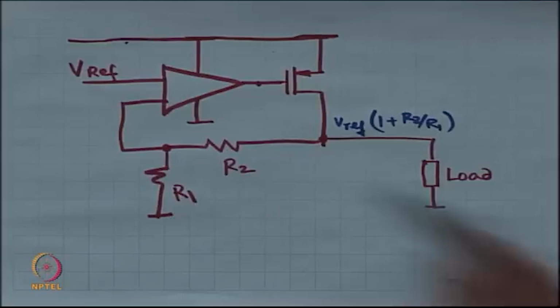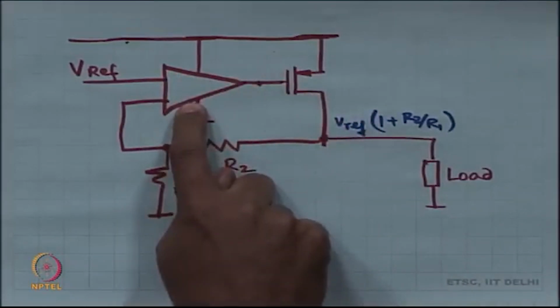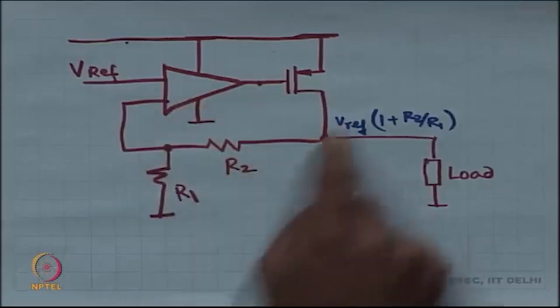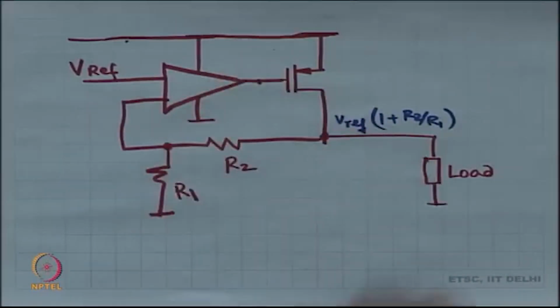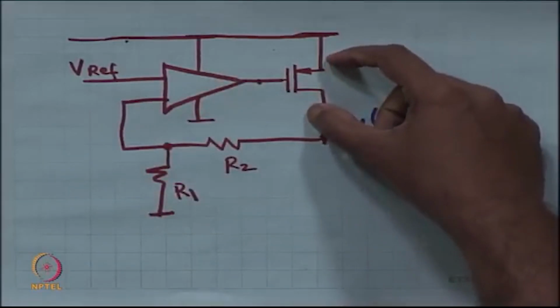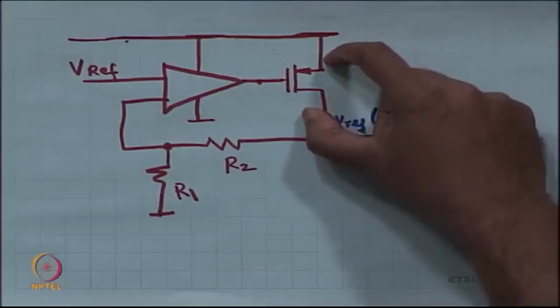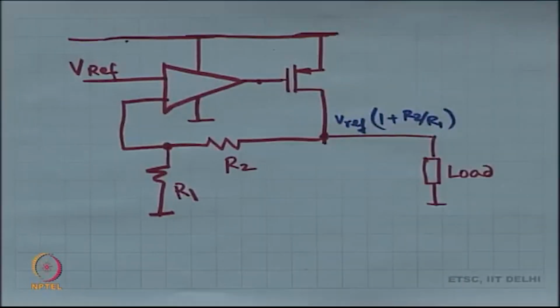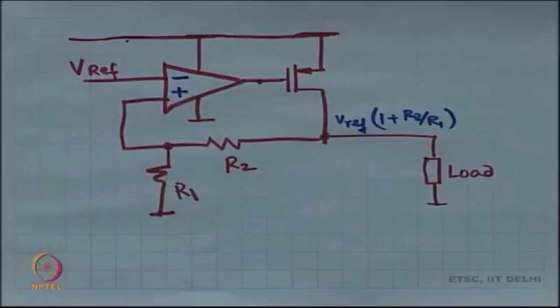How do we do that? If I do the same signs as before, that is plus on top, minus on the bottom, then unfortunately this is an extra inverting amplifier, right, common source amplifier. This is going to invert once again, you are going to end up with positive feedback. So, instead what we are going to do is, we are going to place minus over here and plus over here. So, you flip the signs and that should be enough.